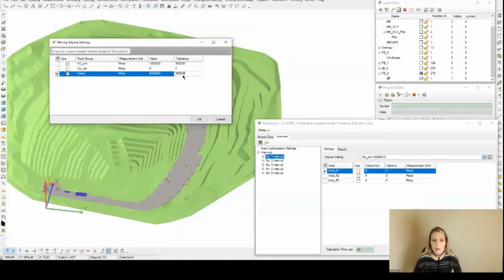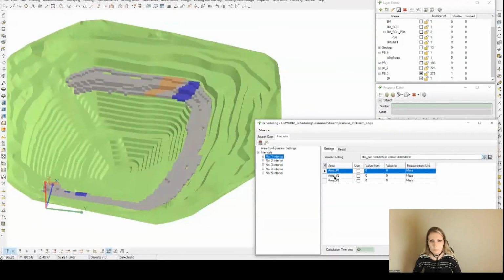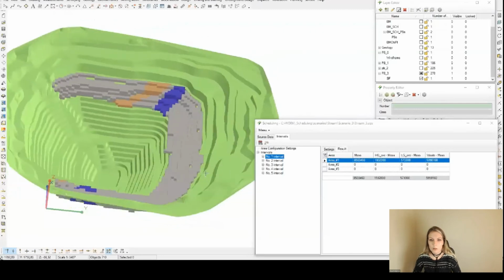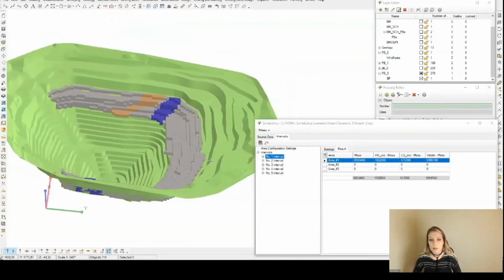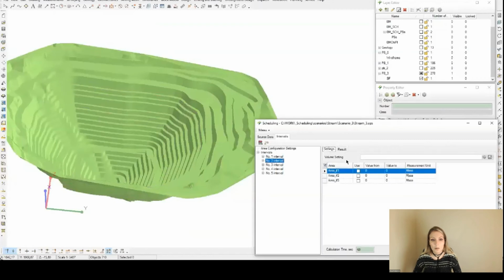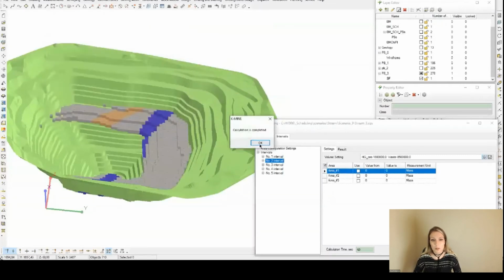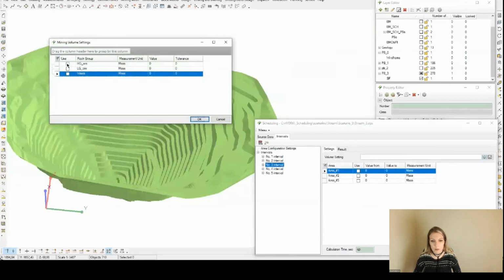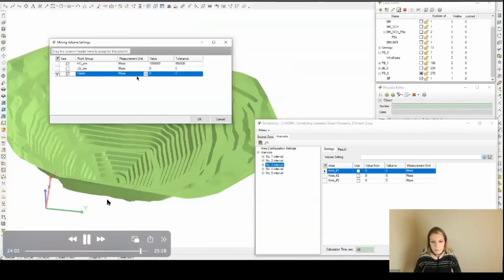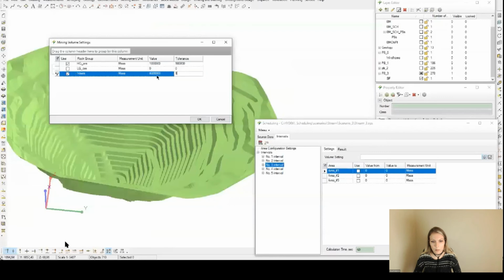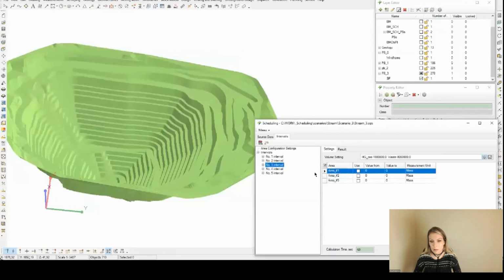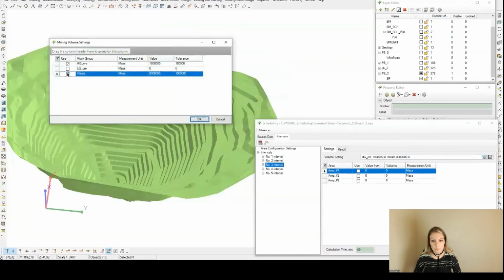And we're going to do the same for other periods. Just when we define only target indicators, and when it's not enough, we will use force loads on each of the pushbacks. This method ensures that it is physically possible to reach the mining position as it is based on actual previously drawn mining positions. And we should use the pushback method to get the most accurate scheduling result.